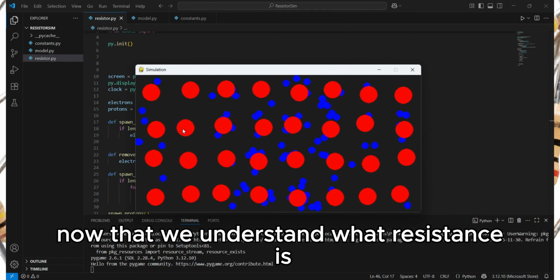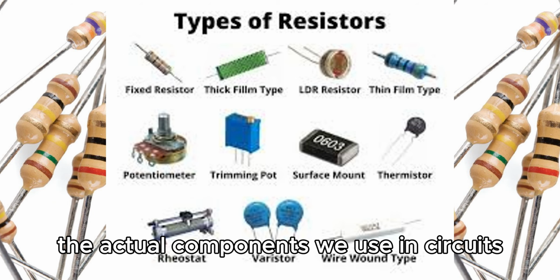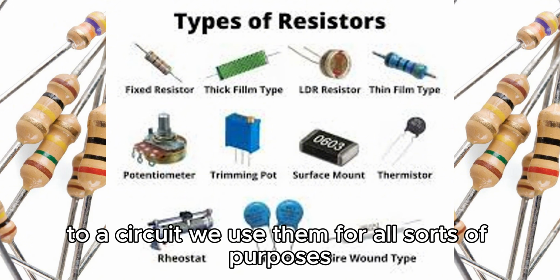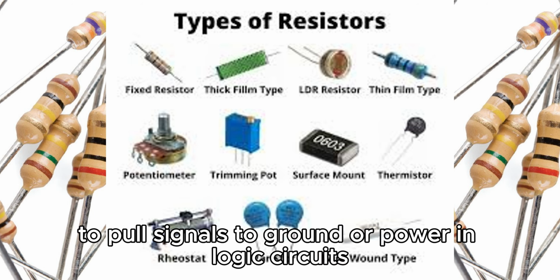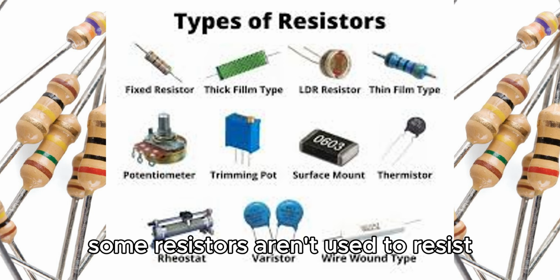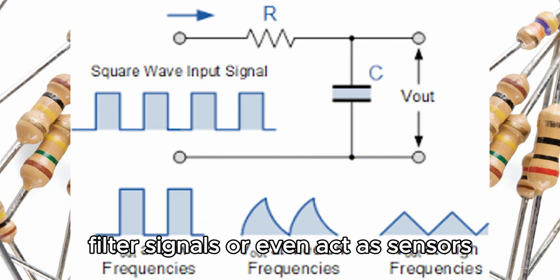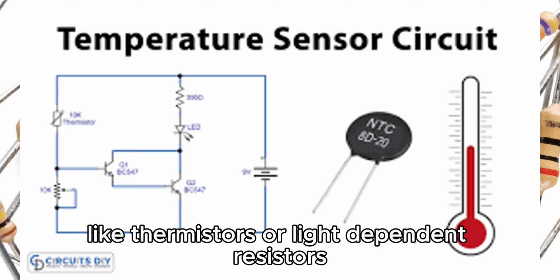Now that we understand what resistance is and what affects it, let's take a look at resistors, the actual components we use in circuits. Resistors are designed to add a specific amount of resistance to a circuit. We use them for all sorts of purposes: to limit current, to divide voltage, to pull signals to ground or power in logic circuits. Some resistors aren't used to resist. They're used to create precision voltage levels, filter signals, or even act as sensors, like thermistors, or light-dependent resistors.